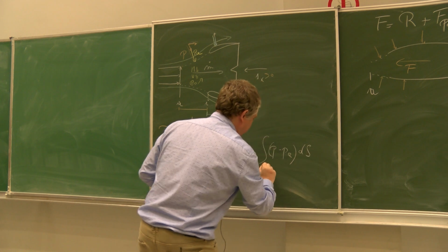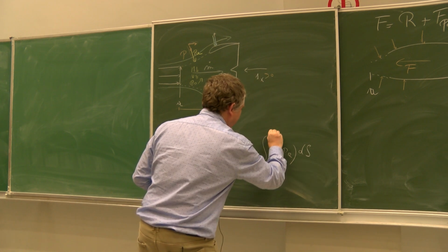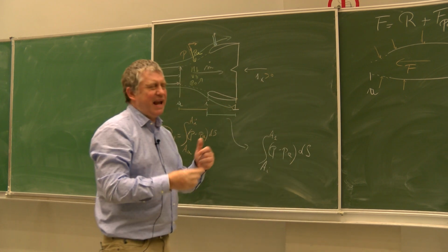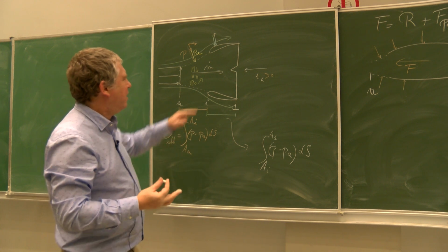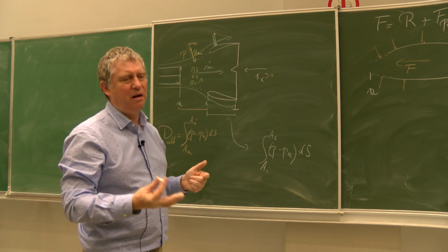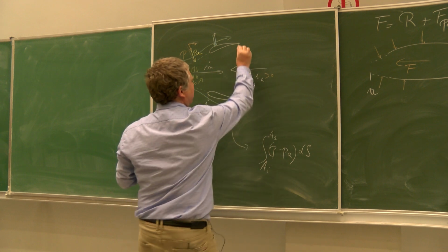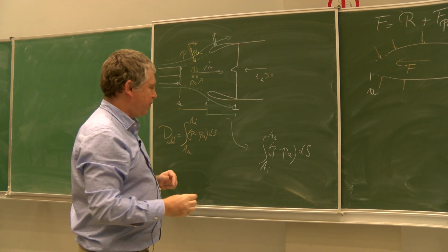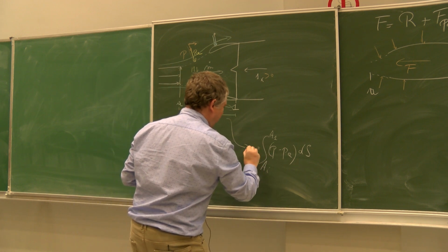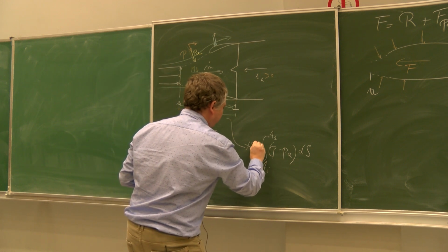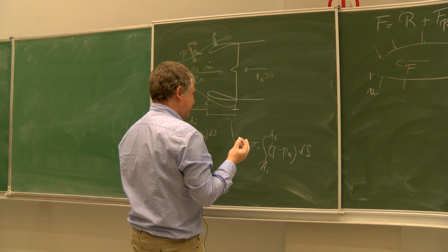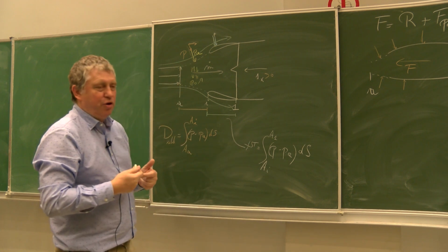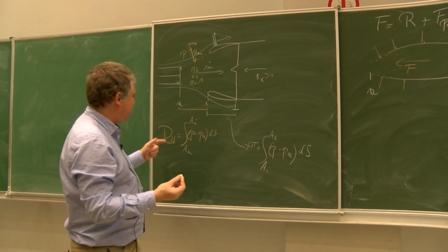multiplied by ds between the section I and the section, let's call it A1, when the flow is again cylindrical, when the nacelle is again cylindrical. This is what we call the lip suction thrust, and that is something that will be of opposite sign compared to this one.